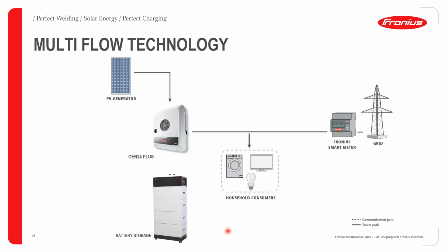So just to summarize the previous slides, with the multi-flow technology of the Gen 24 Plus hybrid inverter, we can have power fed directly to the load from the PV point via the DC to AC conversion, and then have it fed to the grid if allowed for your region, as earlier said. And with this same feature of the hybrid inverter, you can charge the BYD battery.